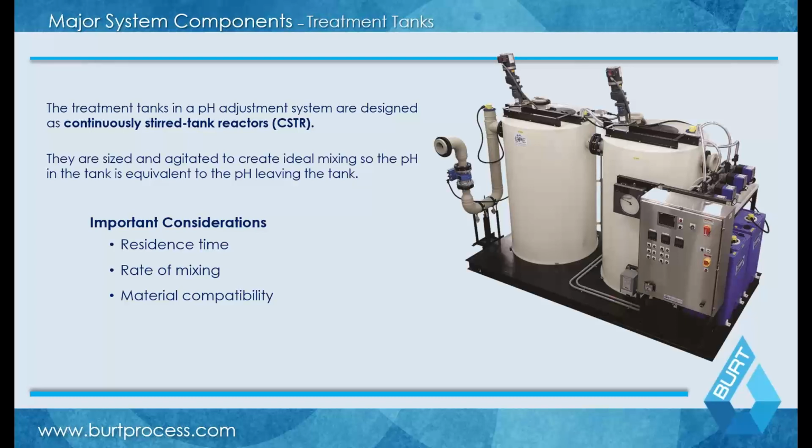The treatment tanks in the pH neutralization system are designed as continuously stirred tank reactors. And what that means is the waste coming into the tank is subject to what we refer to as residency time, and as the waste comes in, it's allowed to then cascade out. You have agitation in the tank that allows you to basically create what's referred to as an ideal solution. So within the actual tank, the pH is uniform, and you're injecting your chemicals in there to allow you to treat the volume of the tank as it has flow coming in or going out in a steady state. The typical residency time for a pH neutralization system is 20 to 25 minutes. It can be upsized to 30 minutes as well if you have more stringent waste conditions.